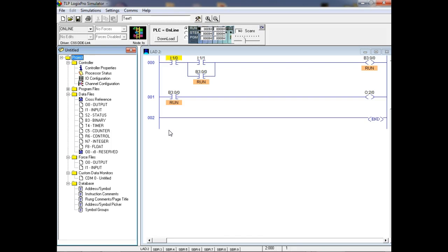And in that way, how many bits do we have? Well, we've got 255 of these things, and there's 16 bits inside each one of those. So we can have a ton of internal coils, I mean, a ton of them. But that's what we need. In motor controls, we call these things control relays. A control relay is a relay whose contacts never go into the power section. All its contacts are inside the control. So if you were converting an electrical line diagram, every time you see a control relay, you'd use an internal contact, right?